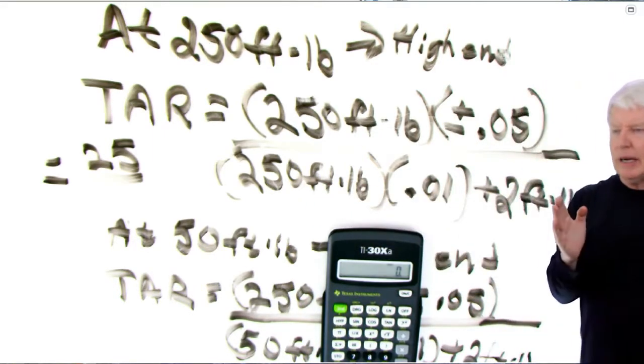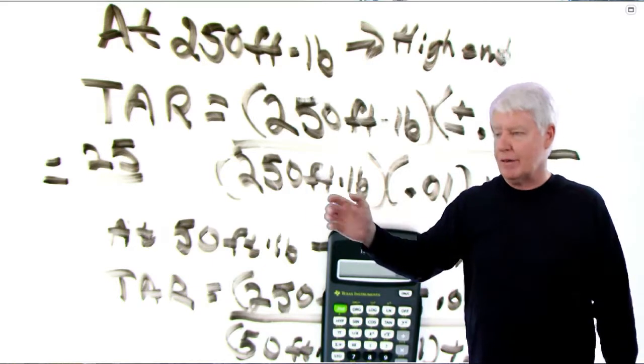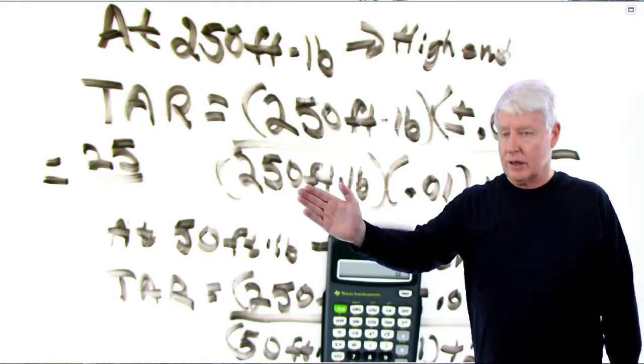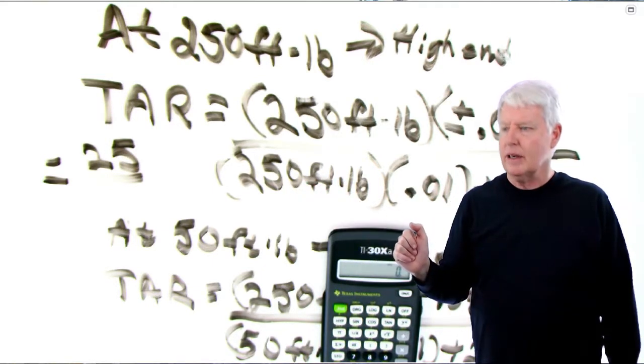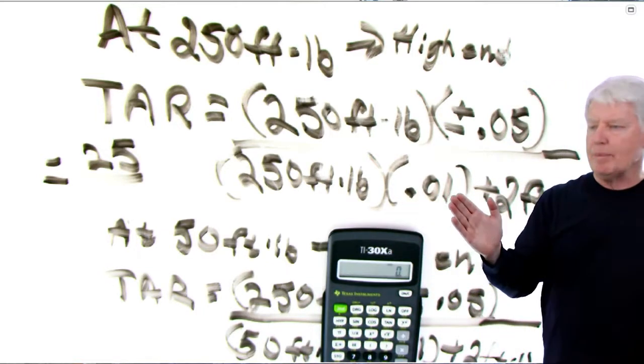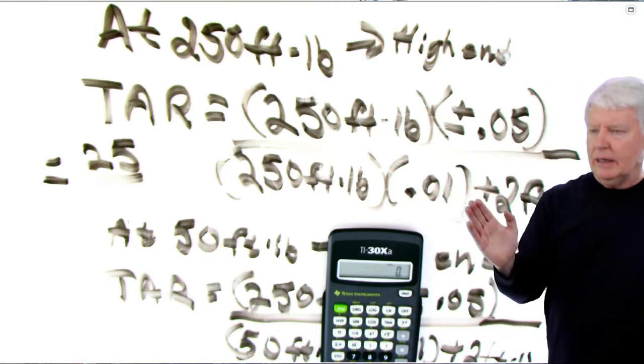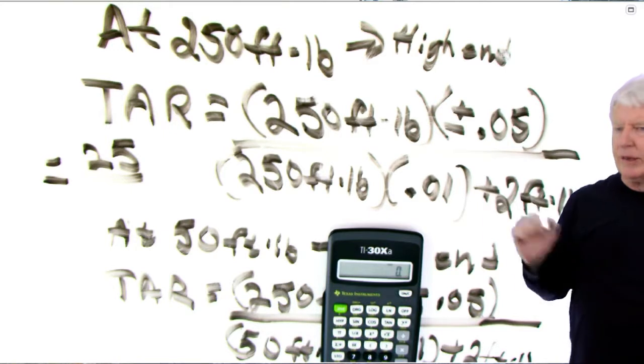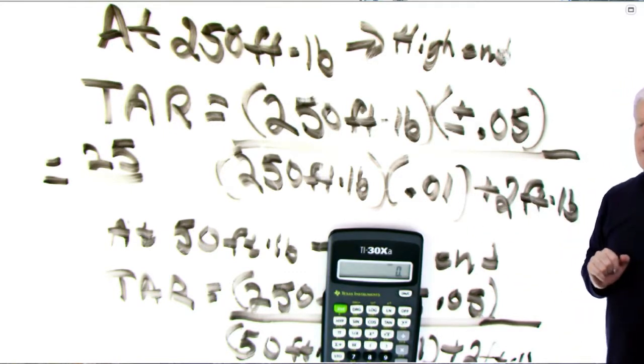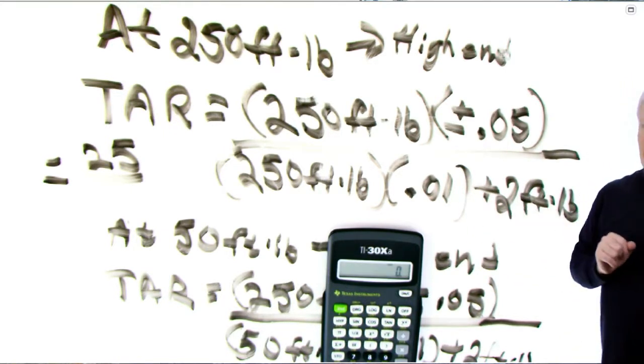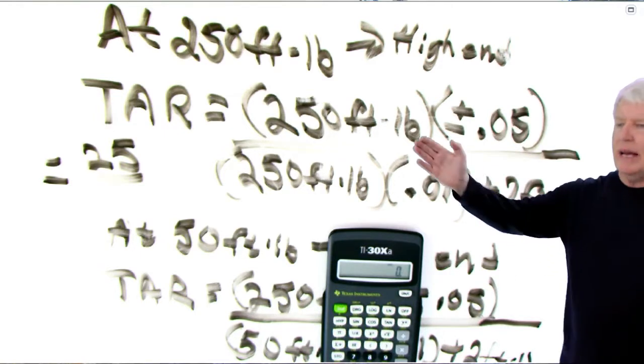And this is the calibration instrument. Remember, it went to 1,000 foot-pounds, but we're only going to use it to 250 foot-pounds, if you'll recall. And that's 1% of gauge reading there, plus the 2 foot-pounds. So we got that right out of the test question. So let's go ahead and do that.